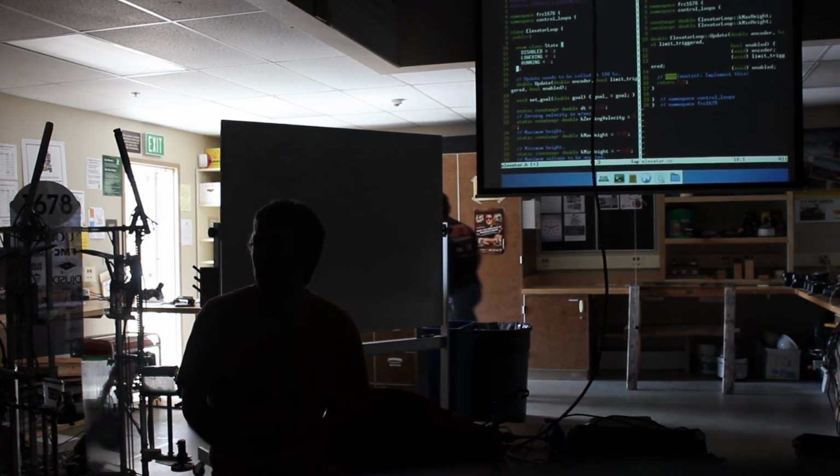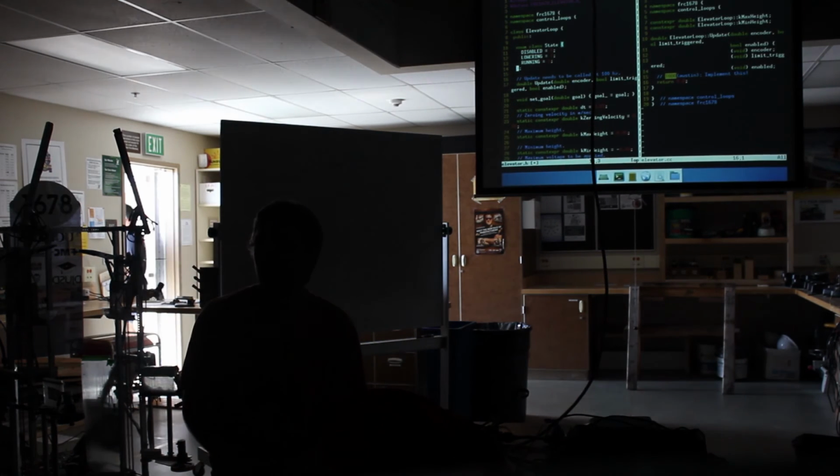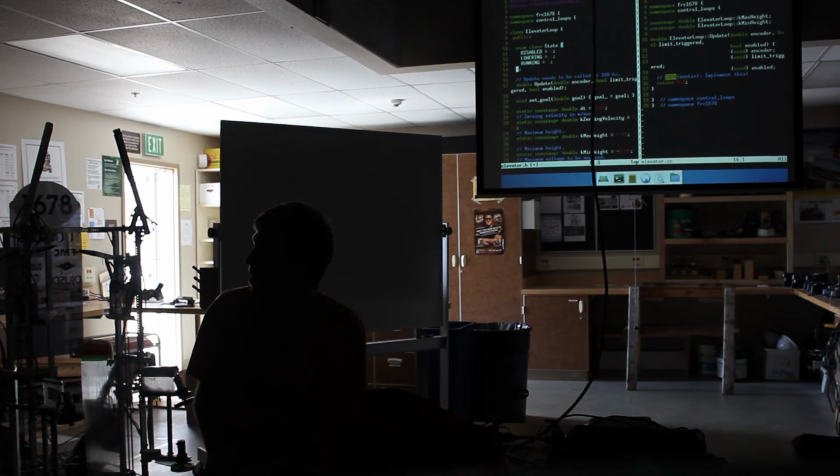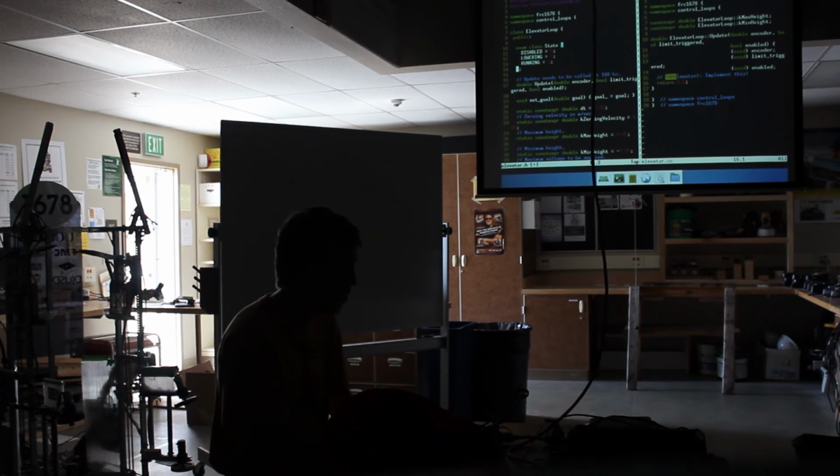That way, say your elevator shuts down because you detect the encoder came unplugged and you can't control it anymore, then you shut the elevator down, but the drivetrain still works. So instead of it just erroring and going all the way up, you keep your value in high. We had a fault on one of our sensors at SVR in, I think, the semifinals this year, and it shut the superstructure down. That happens.